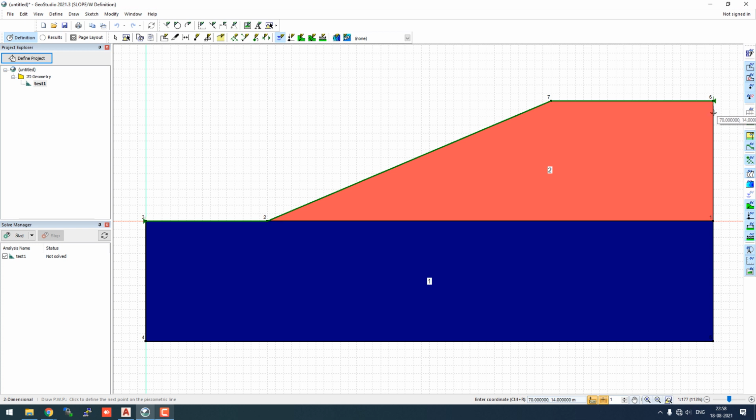You can see the coordinate system when I hover. So I'll go to 14 and create a straight line at some distance like this. I will merge this straight line under the point 50, 15. So 50, 14 will be the second point of the piezometric line, and the end point will be the toe of the slope. Finishing it here and clicking on escape.